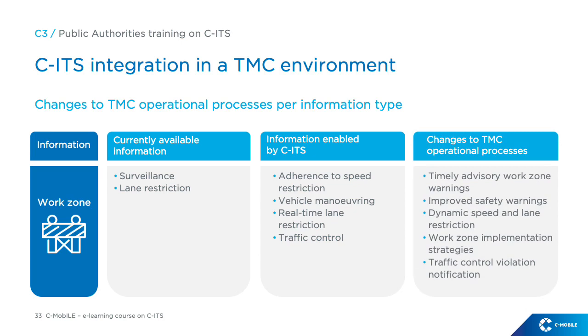The changes to the TMC operational processes allow for the provision of timely advisory warnings to travellers in the proximity of a work zone and the surrounding areas, improved safety warnings when approaching or within a work zone, dynamic warnings about speed and lane restriction, modification of work zone implementation strategies based on traffic response, and traffic control violation notification.